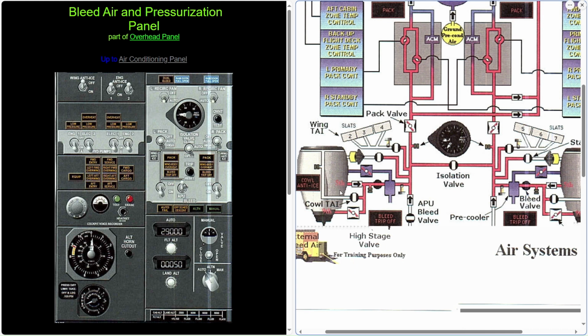So that is all the information we have. The cowl anti-ice light, that light is a disagree light. It's like saying, well, you asked for the cowl anti-ice, you're not getting any pressure in it. All right, so then we go a little bit up further past the starter. We get to the wing anti-ice system, and this is for the slats. You see 2, 3, 4 slats here on the side, 5, 6, 7. So it's the mid flaps that you're talking about. You don't do one, which is out on the wing, but you do all the mid or the inside.